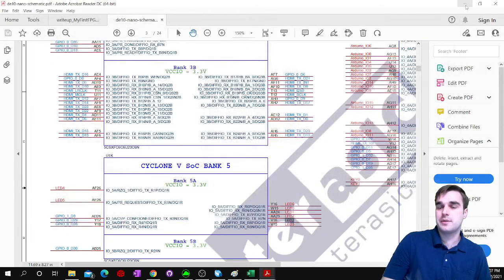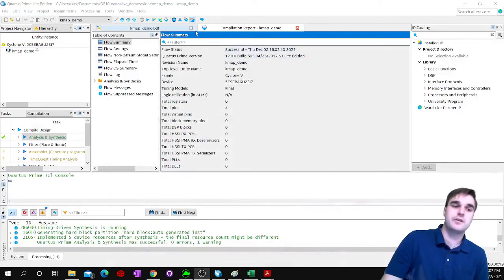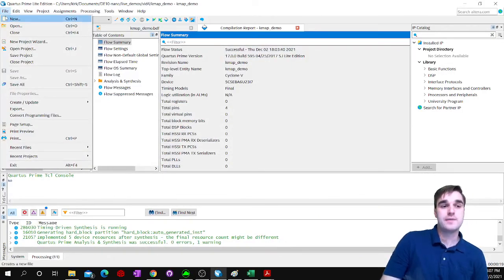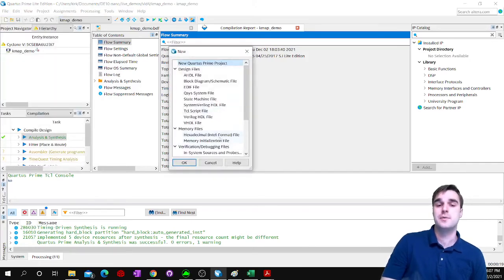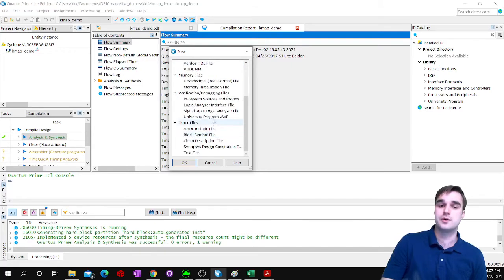Let's go ahead and close the pin assignment planner. Go back to Quartus. And let's get our waveform going. Our waveform is going to allow us to check. Actually, it would make more sense if I would do the waveform before going through the work of the pin assignments. Because the waveform is supposed to tell you if you did things right, if this is really doing what you want it to do, before you go through all the work of getting it programmed to your board.